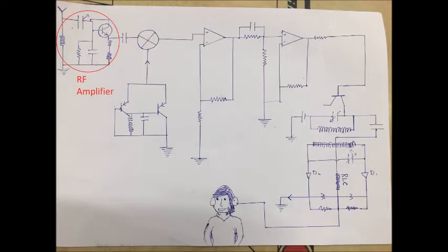How this is done is that the inductor and the variable capacitor, which you can see in the figure, form the frequency close to which the bandwidth is formed, and the BJT acts as an amplifier for the same. From there, coming to the oscillator, it is gang coupled with the RF amplifier so as to provide a mutual and individual frequency to work with. So it provides the same frequency to the mixer as well. Now the main part of the mixer is that it gets input waves from the oscillator as well as from the RF amplifier and provides a mixture, say F1 plus F2 and F1 minus F2, F1 and F2 being the separate frequencies.